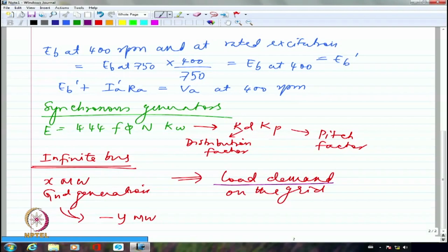If the generating station realizes many loads have been shed off, then they have to reduce the amount of steam that they are pumping into the steam turbine. Right? If they see that more and more loads are coming up, they have to notch up the steam going into the steam turbine, so that the speed is a constant; the torque is the one they are changing by inputting different amounts of steam. That's all they are doing. The speed is a constant.